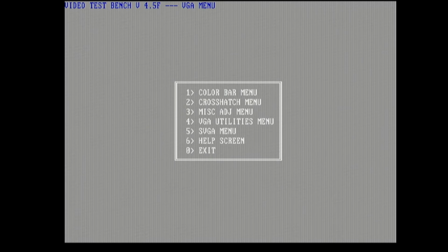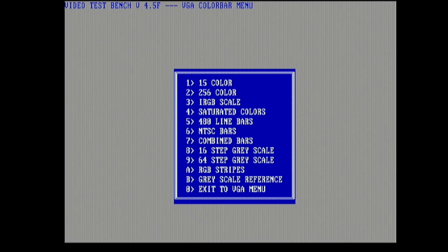I'm just going to show one of the test patterns here, and I'm going to record on the Logic Analyzer just to show you what all these changes that I've done have been. So this 480 line bar is actually using graphics, and you can see here that the interference we got there seems to be because either the addresses that we're reading and writing to are not coming out quite right. See, there's a bit of bleeding of the pixels going into the other pattern. It should obviously just all be the same color.